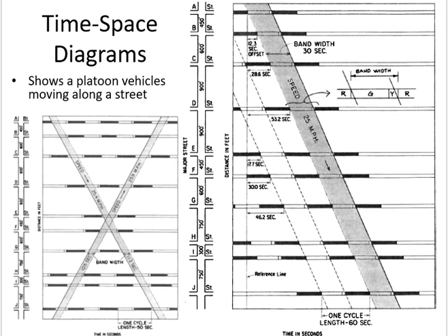So the first car can leave during green, right? When the green starts, the first car can leave, right? The last car will leave when? It is yellow. End of yellow, right? So the first point of this progression, we call it the progression, this is the progression of vehicles, the movement of vehicles from the first intersection to the last one. So I know how to get the first point. First point is start of green. Then start of green, start of green, just keep on going in the same line.